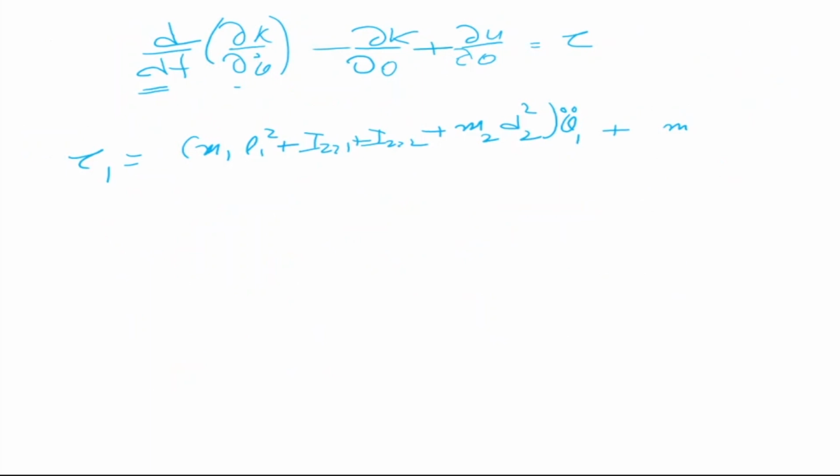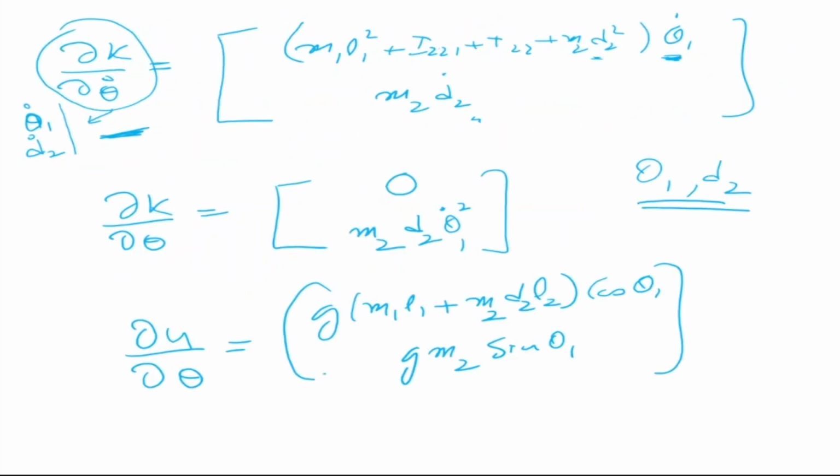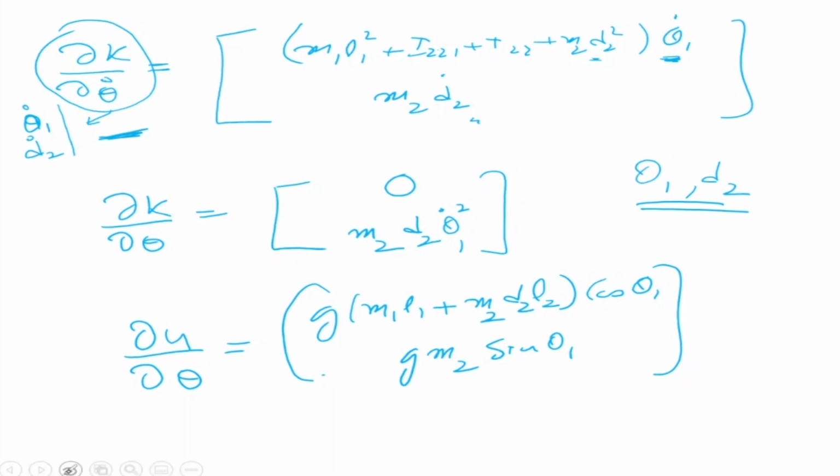So let us stop here today, and we'll continue in the next class and look at another example of Newton-Euler, and we'll also look at examples of Lagrangian-Euler. Now Lagrangian-Euler is good to implement in MATLAB because most of it is matrix multiplications, and hence it is sometimes preferred over Newton-Euler. Newton-Euler is essentially vector based, okay, whereas Lagrangian-Euler is basically matrix based because half m v squared is there. So we'll stop here today and continue in the next class. So thank you.